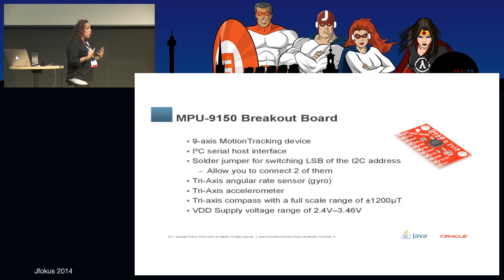Okay, so why I needed an accelerometer and a gyroscope. What I wanted to do is figure out if the user was tilting the device or not. Tilting the device could be tricky because of what happens with the accelerometer reading. The accelerometer is actually reading acceleration against gravity. So we can actually find out the angle we're making against gravity. Okay, so when you tilt it, if we are like this, I can actually measure this particular angle. Okay, I can find that out.